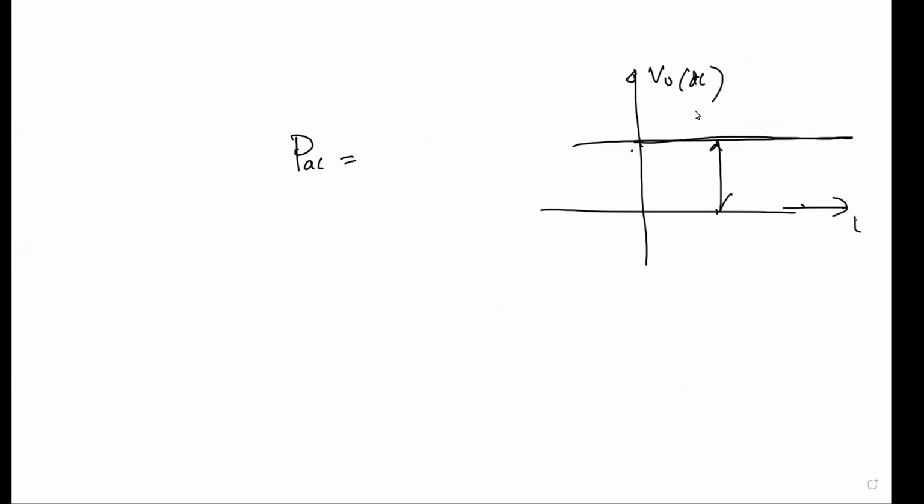Sir, can you repeat again, sir? So this voltage I am showing with respect to time T is parallel to the T axis. Is it not the DC voltage? Yes, sir. Okay. What will be the RMS value of this one? Suppose this is T, this is 2T, and this is 100 volt. What will be the RMS value? Same. The RMS value should be the same.